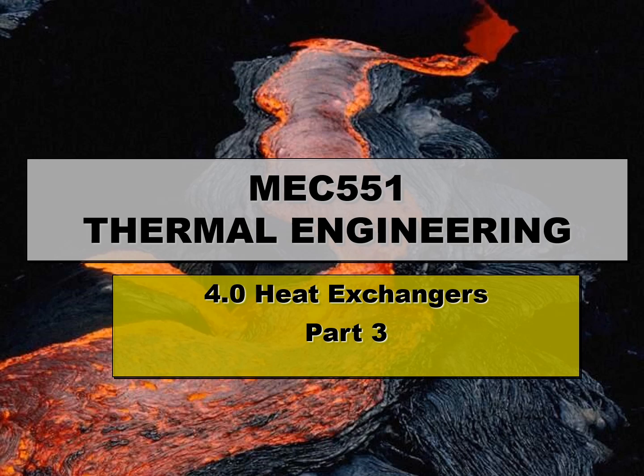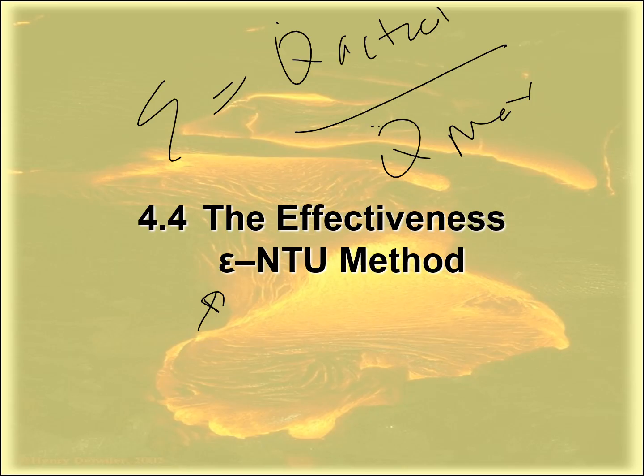This is part 3 for the 4th chapter, heat exchanger. So we're going to look at the effectiveness-NTU method, which is the second method for the heat exchanger analysis. The effectiveness-NTU method is derived based on the effectiveness equation, which is given by Q actual divided by Q max.